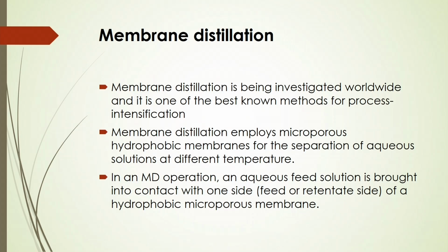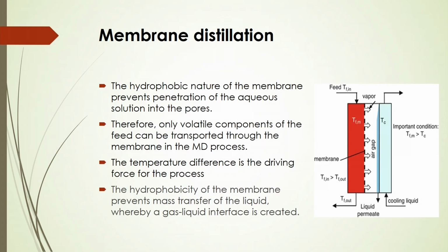In a membrane distillation operation, an aqueous feed solution is brought into contact with one side, that is the feed or retentate side, of a hydrophobic microporous membrane. And the hydrophobic nature of that membrane will prevent the penetration of the aqueous solution into the pores. Also, the temperature difference is the main driving force for this process, and therefore, only the volatile components of the feed can be transported through the membrane in the membrane distillation process.